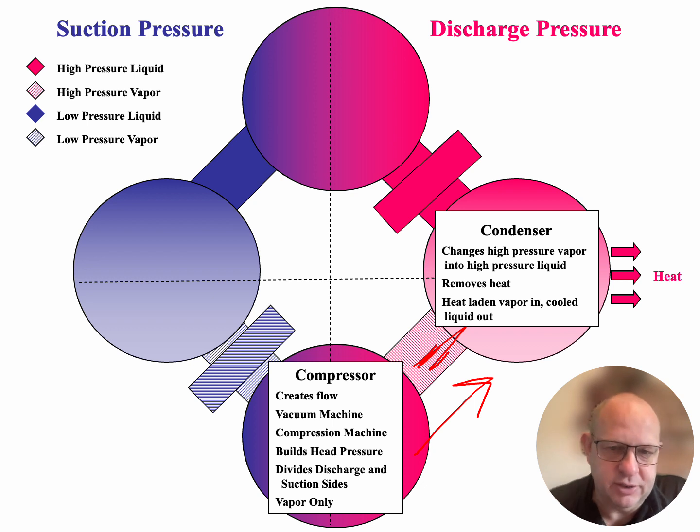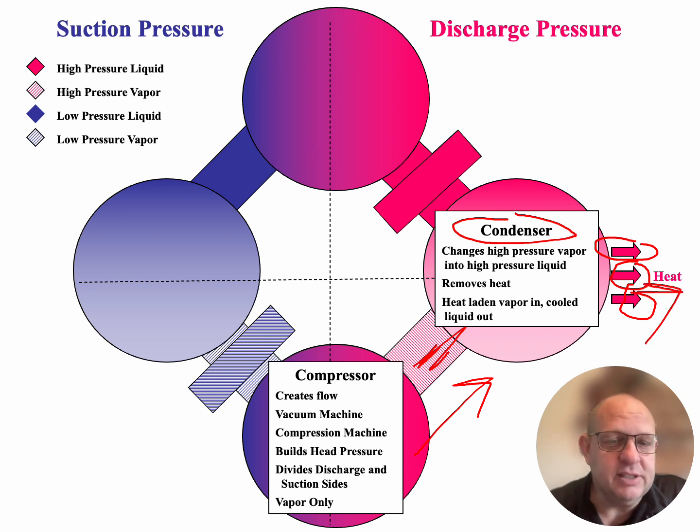which is our condenser. Now, here's our condenser. The purpose of the condenser is to take the heat out of the system. Don't forget that on your diagram to go ahead and put these arrows in by the condenser, showing us that the heat is actually leaving the condenser. The heat is leaving the refrigerant, and it's going to be passed from the refrigerant into the air temperature that's passing either outdoors over the condenser. So that refrigerant is going to be